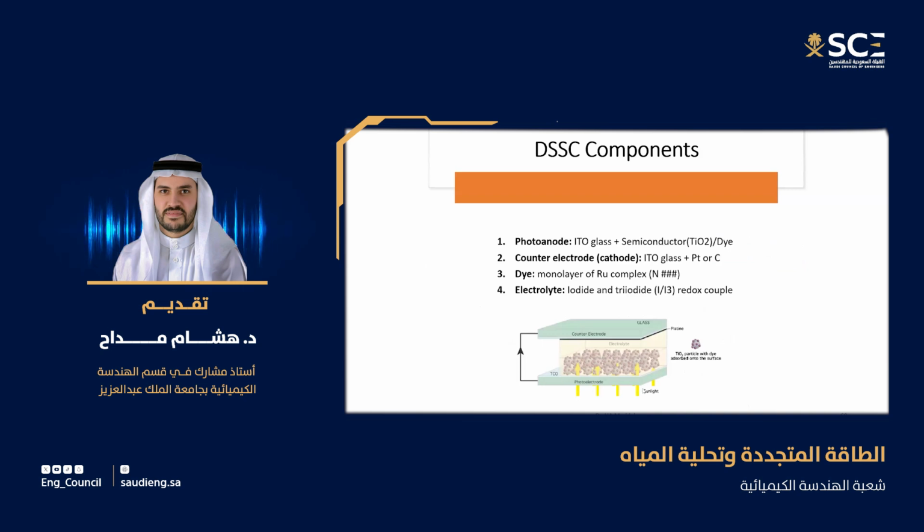Look at the representation of this system. If you look at the schematic or the chart, you have the photoelectrode and counter electrode. Photoelectrode means you have anode and cathode, plus and minus again. Then you have the dye in between, and then you have electrolyte material here. This is a different material from the silicon solar cell. In silicon, you have silicon only as a semiconductor material. Here, what is the semiconductor material? We use titanium dioxide. This is also environmentally friendly, because it's not toxic, and we use dye.